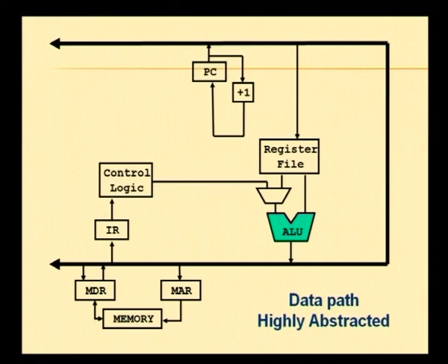If you look at this picture that we have, let us look at what will happen. Okay, where will I normally store this again? So, look at what we talked about right now. Some address was given to the memory address register. This address is the address of the instruction that I want to fetch. Okay. So, I said we will assume that this value is known to us somehow, and normally this address would be stored in this program counter. This program counter is a special register which will be there in the processor. This program counter will have the address of the instruction that is to be executed next.